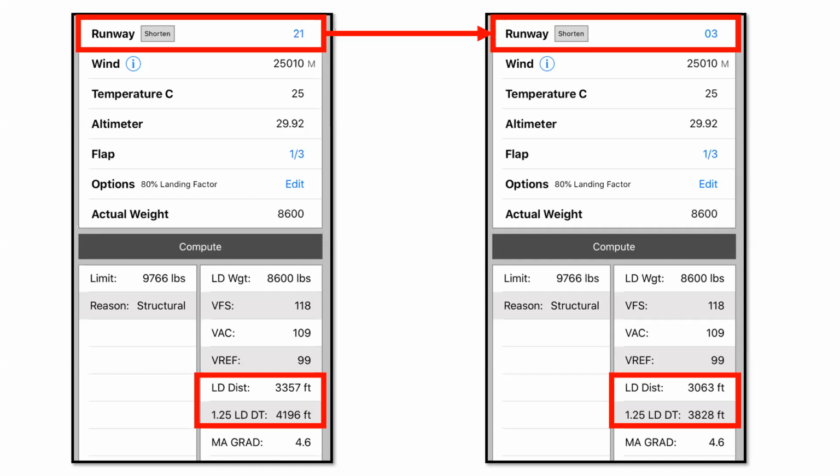We would expect a test pilot to stop the airplane in just a little over 3,000 feet, so 300 feet less in the absolute best case situation. Or with a little bit of a safety factor, we could see that we would be expected to stop the airplane in just over 3,800 feet. Now, in both cases, even with the safety factor, the runway required was less than the runway present. Again, this particular incident was a direct result of a very unstabilized high energy approach.